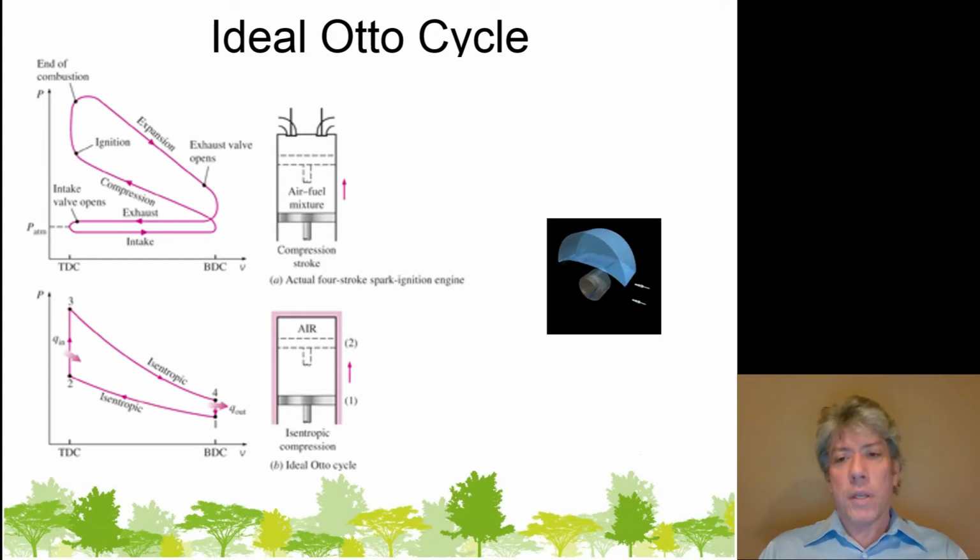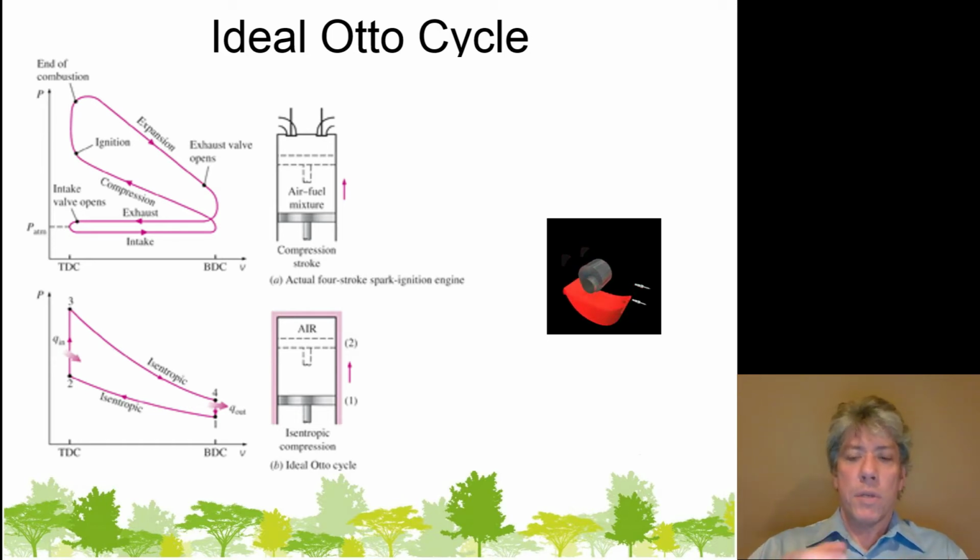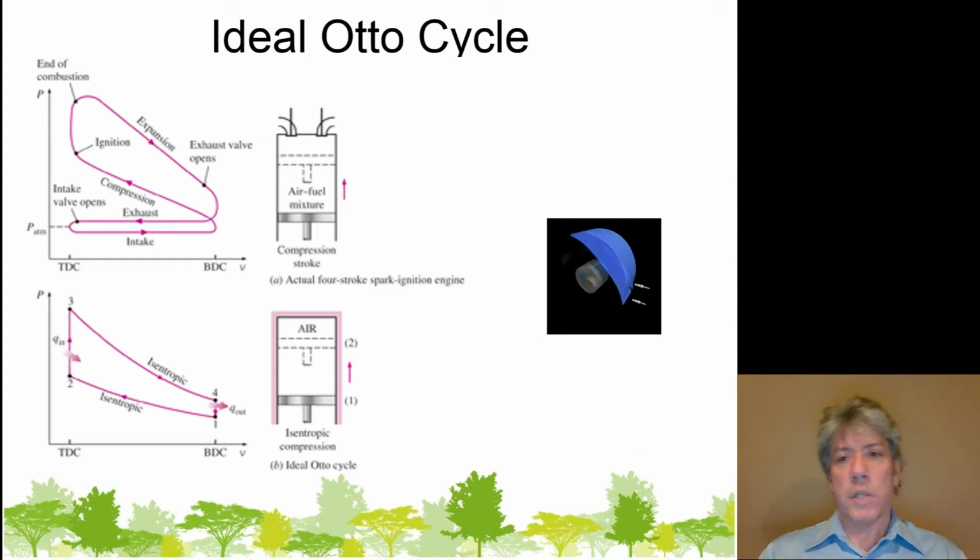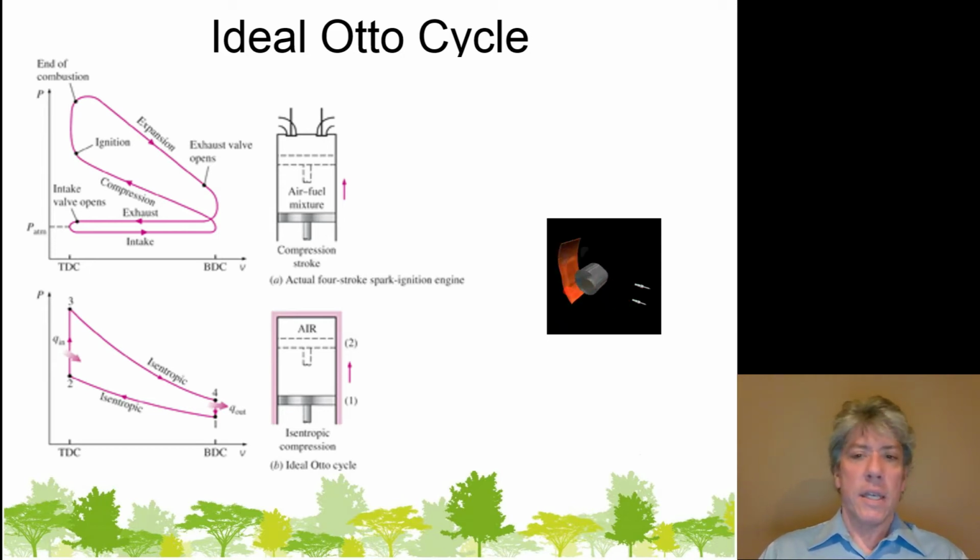The problem with it is that the part that's not shown is the rotor, and the rotor is almost a triangular shape. And the problem with the rotor is that instead of being a piston, which has a large cross-sectional area for very small perimeter, so it's easy to seal as it moves, in this case the rotor had 3 lips that had to be sealed, and that wasn't so bad. That wasn't much line length. But then the side faces of this very large object had to be sealed, and you run into friction problems there. It's difficult to seal. And so that really is the Achilles heel of these engines.